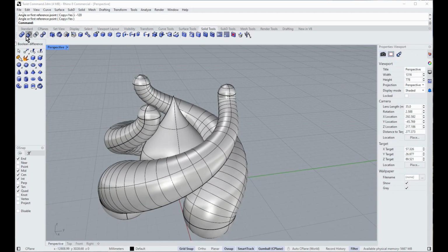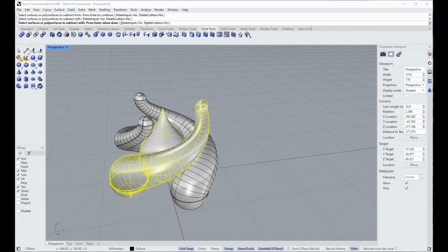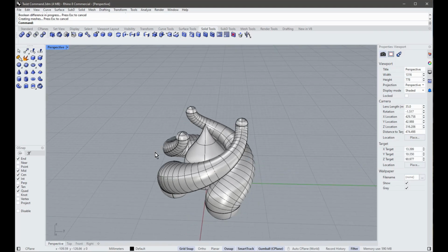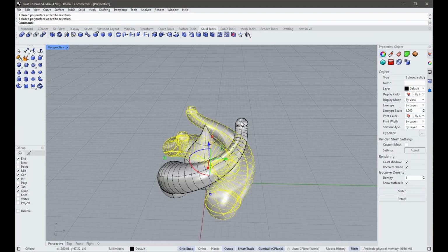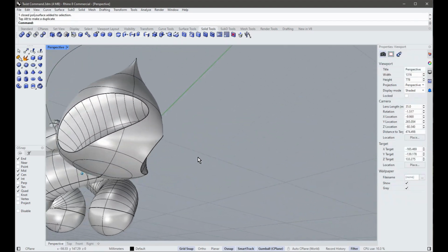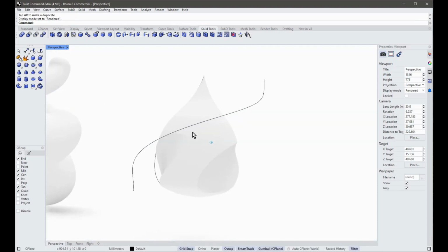Now we can do a Boolean difference. It's also called Boolean subtract in other CAD software. So select your center body, right click, then select these 3 little horn looking guys. And I kept them on. There might have been a setting for that, but I'll just take these, move them out of the way, and now you have that fancy looking thing. And we go into rendered.